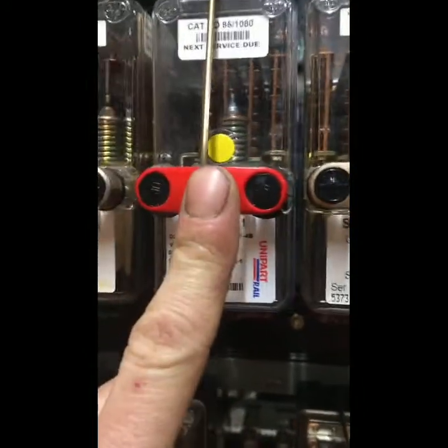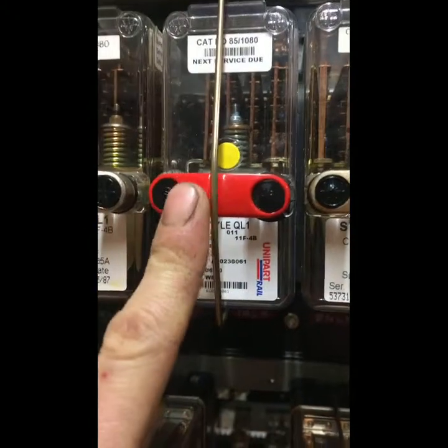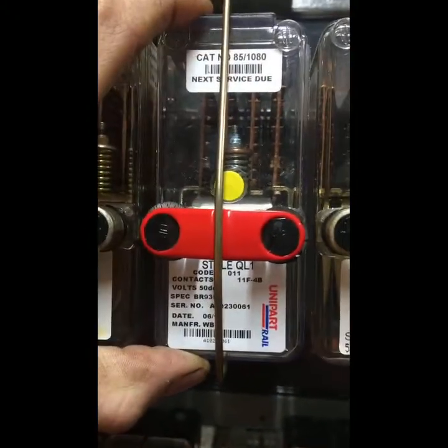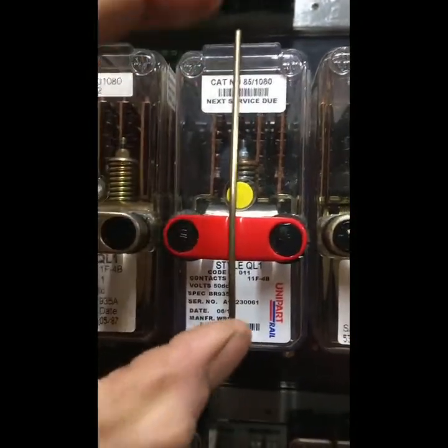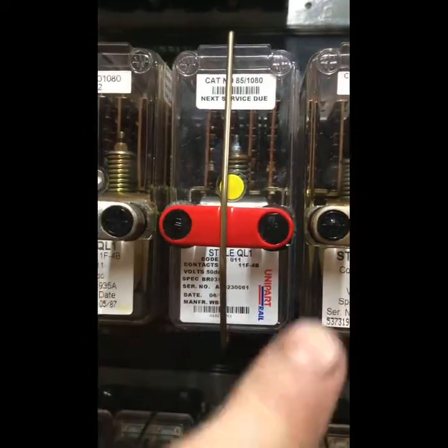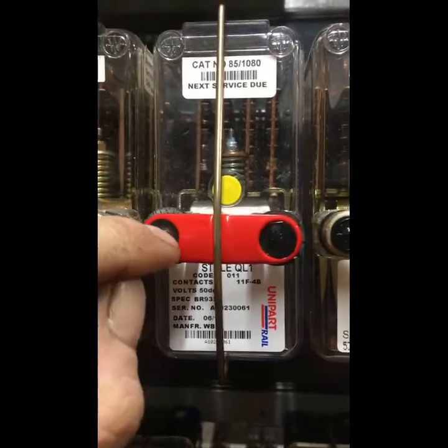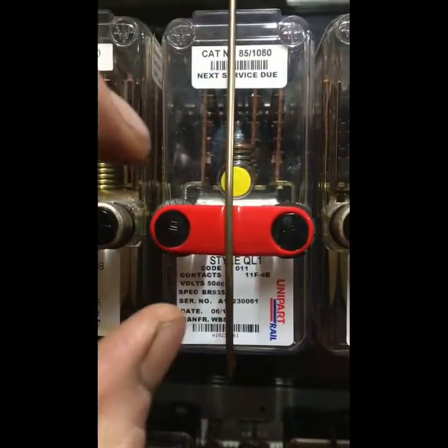And you will notice straight away that these have red fronts on them. This implies that it is a latched relay. If these were removed and the relay was up, it would remain up. It is magnetically latched in that position. You have to drive the secondary coil in there, which is the dotted coil that you saw in the diagrams, to be able to delatch them magnetically. You have to destroy that magnetic field inside to delatch them.